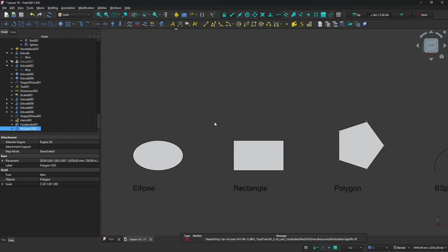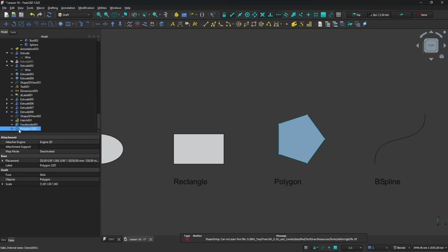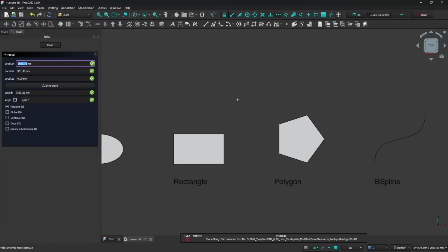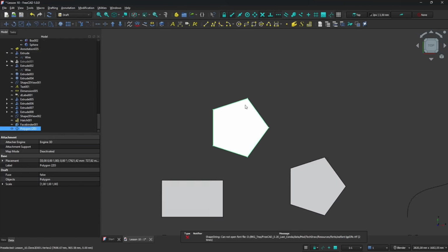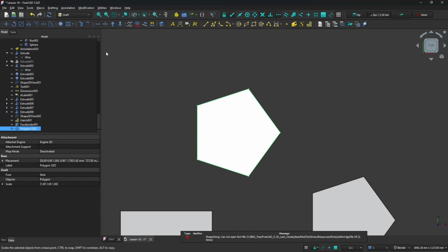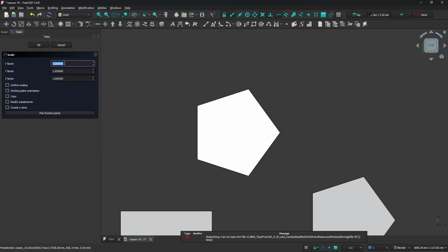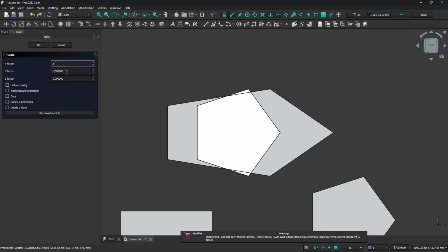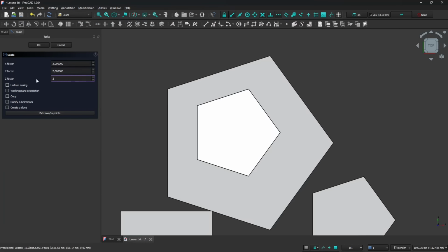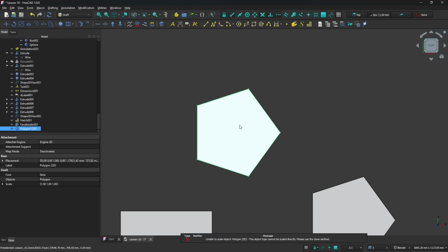If I create a clone, it is represented with something like a sheep, so I cannot move it. And instead of resizing using the resize tool, which doesn't work, the other option in this case is to go into the clone and just use the scale inside the clone.